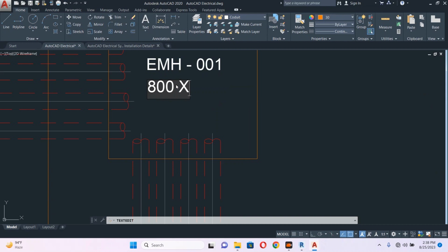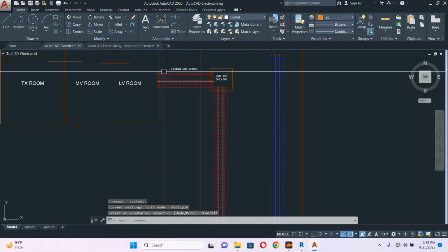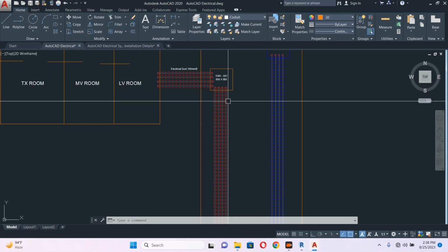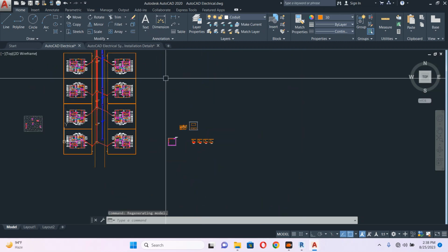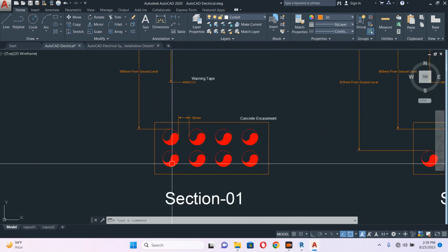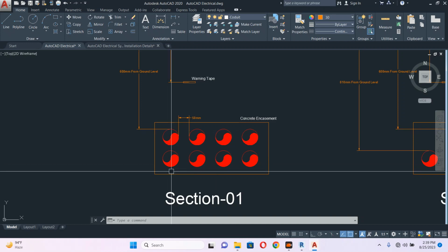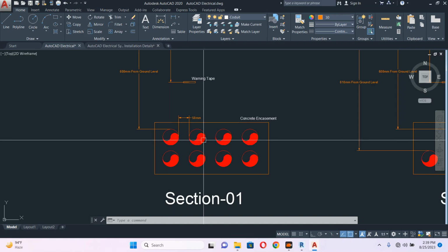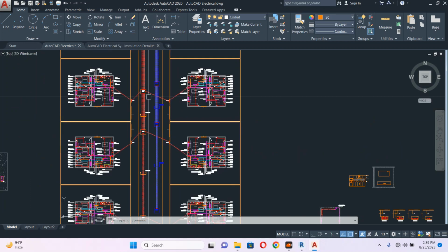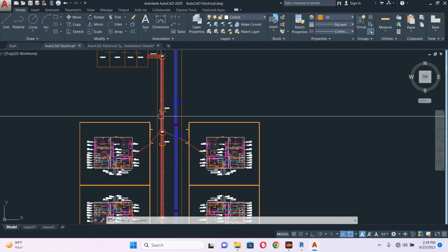So the depth, I didn't mention yet because I don't know the depth. We have to calculate, because I still haven't finalized how much cable will be here. Here we can decide. So this one 600, 160, 160, 320, 920 plus 50, 50. I think 1020. So let's make 1200 depth. All the manholes 1200 depth. 1, 2, 3, 4, 5.